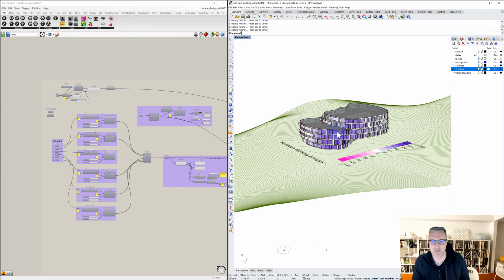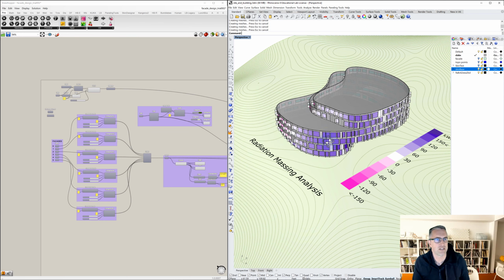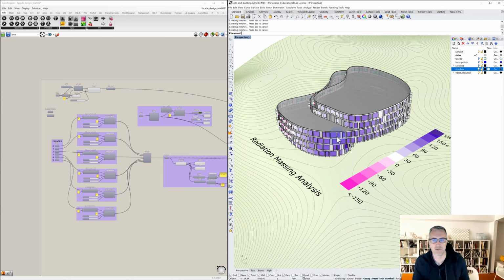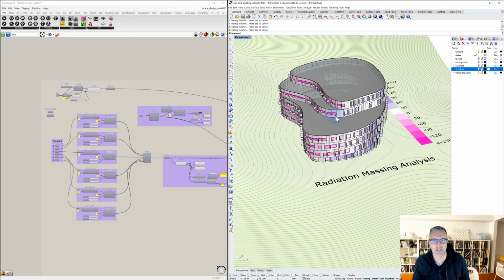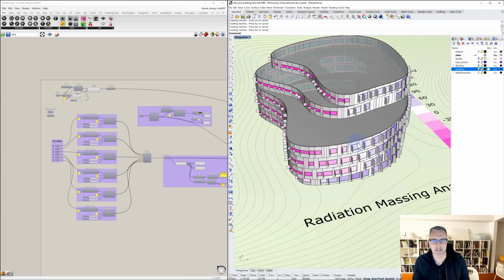With the SkinDesigner tool, we also have options for either vertical or horizontal shading, the glass and the panel. As we look closer, what I'm doing is randomizing the size of the panels. And as the panels drop below a certain dimension, I think 3 or 4 feet, the window is removed as well. So we're going to embed some intelligence within those elements.